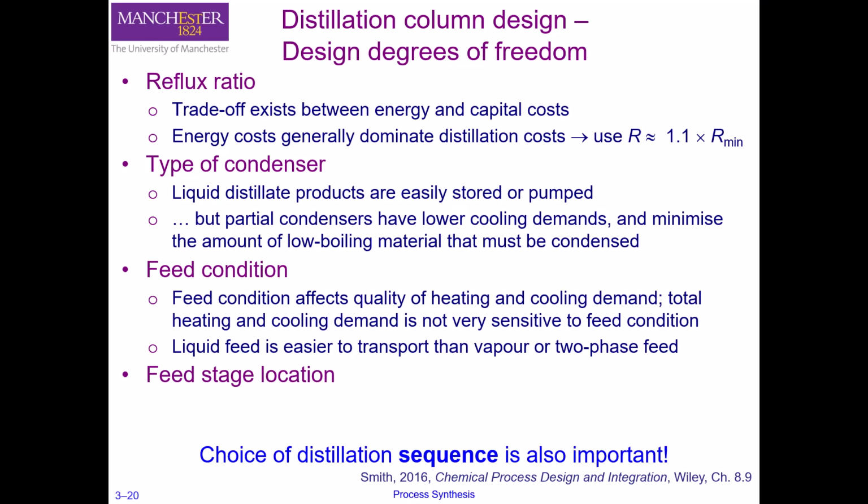This translates into the amount of heating or cooling required in the reboiler and in the condenser. The heating or cooling of the feed affects the total heating or cooling of the system. So it is very important that we understand what the best feed condition is.